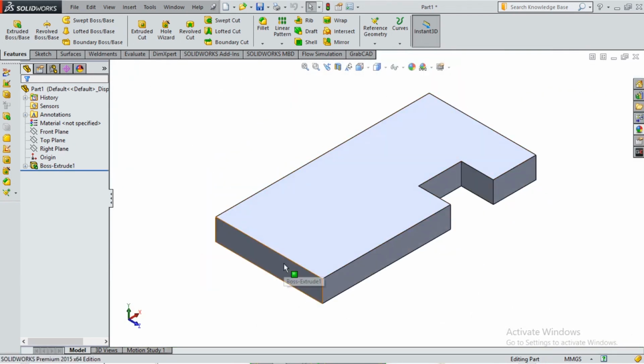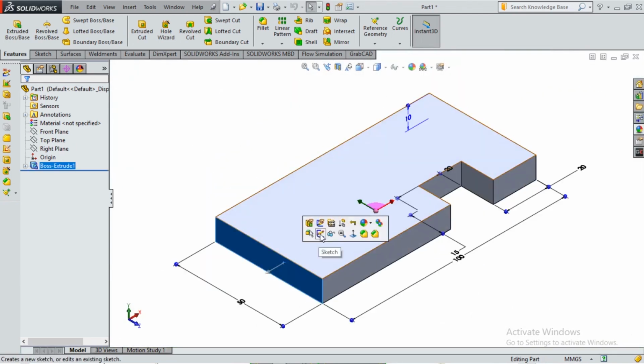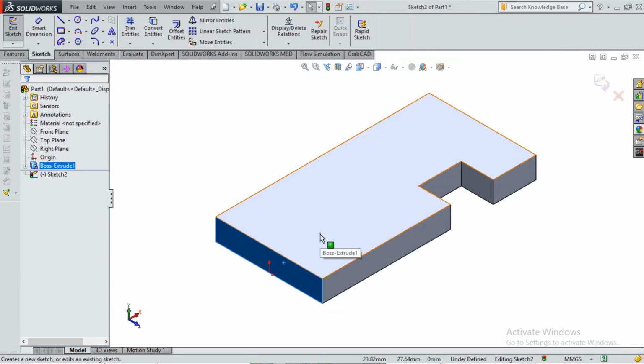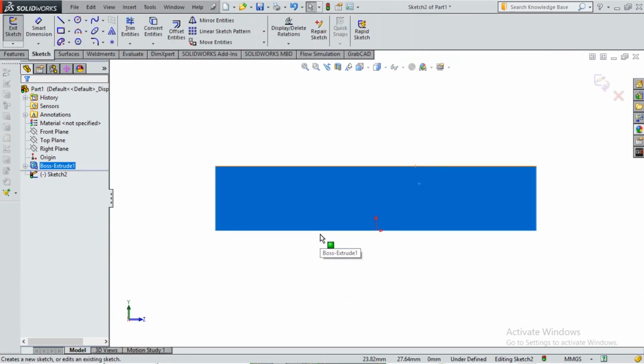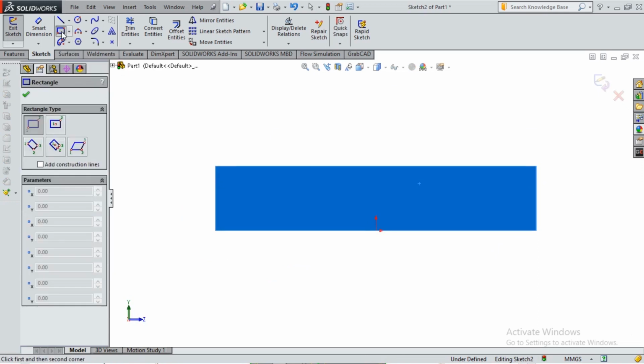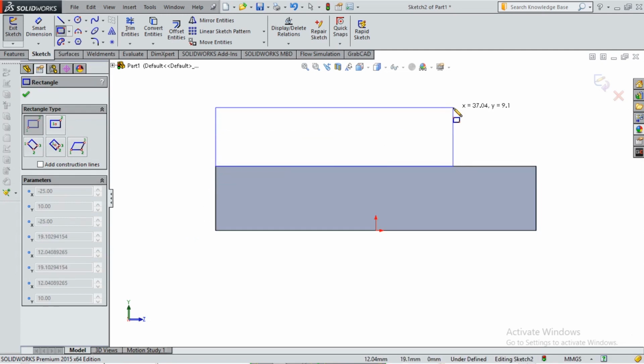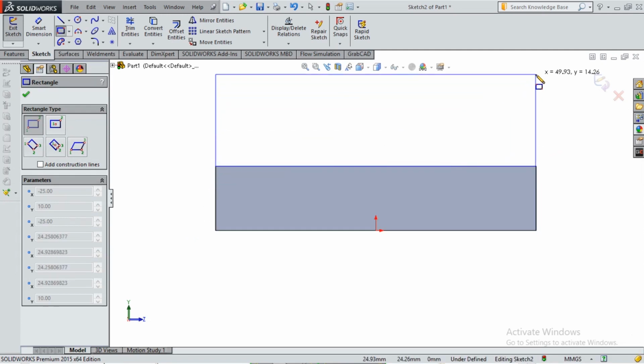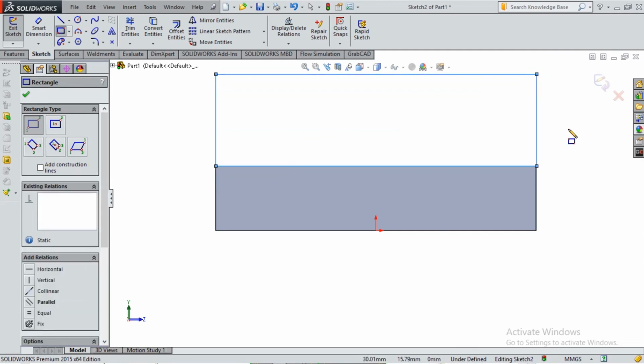So now, we've not done much about faces and sketch planes. You see how I just selected that plane to sketch on it. Now I'm using my corner rectangle. That seems appropriate for me this time. If I used a center rectangle, it wouldn't give me what I need.